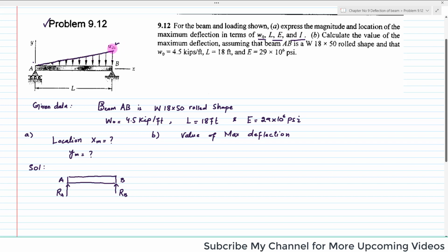So in order to convert this uniformly increasing load into a concentrated load, you can see this is a triangle. So the conversion of this load into a concentrated load is the area of this triangle, 1/2 W0 into base, where W0 is the height and the base is the length of this beam.